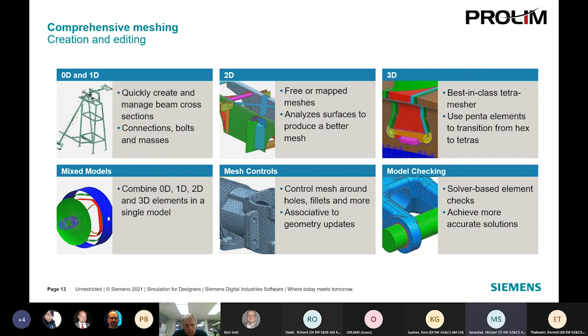And that's something that you don't always see in other designer level tools, having the capability to do all of that work. And then ultimately, like we already talked about, the mesh controls that are important for the sizing and model checking, right? Are our elements good? Because if not, we'll get some really bad results. We're always going to get a result, but how accurate are we? Are we really mimicking the real world performance? So next.